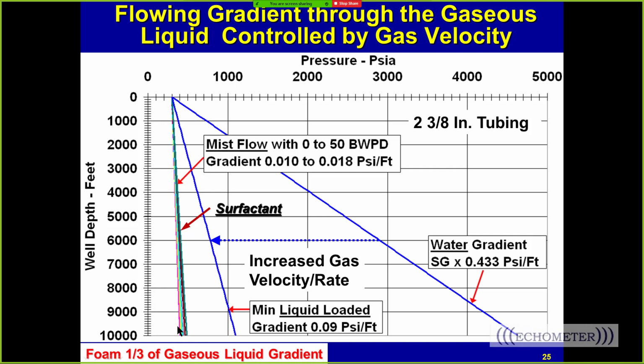acting on the formation. And so if you use Turner and you say, well, you're below the velocity required to get the liquid out, you're liquid loaded, then you're going to be at a liquid gradient somewhere in this range or higher. If it's all water, it could even be higher than that. So it can be really heavy.